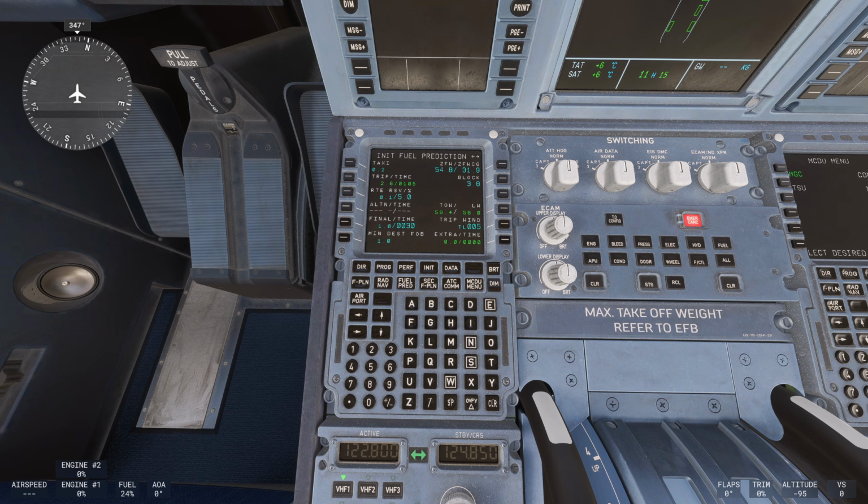Now that we've got all that information put into the MCDU, notwithstanding everything else we have to set up in the cockpit, but those are in other and previous videos, the aircraft is essentially ready to take into the sky. Now there are things you need to put into the MCDU while you're in the air, and probably one of the most prominent entry pages is going to be your approach phase on your performance tab.